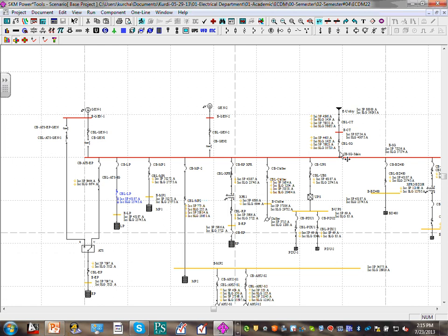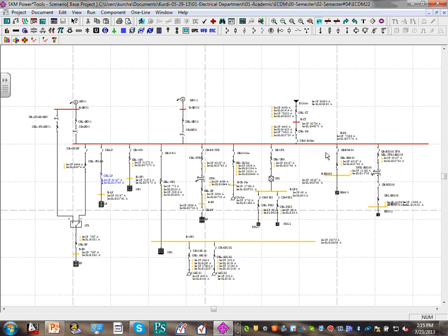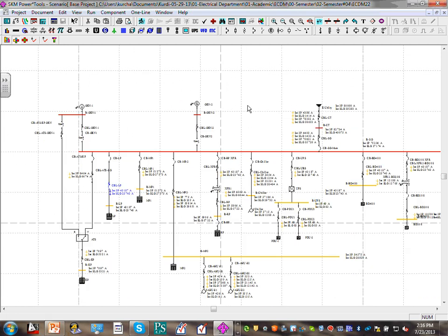In some projects that I was involved in, we run them without the generator, and then we write that if you are to run the generator in parallel with the switchgear, you will exceed the capability of your switchgear. Typically now you cannot run in parallel, right? You can't run except momentarily to switch yourself off the grid. Otherwise, you're going to be in the business of production. And there's a lot of EPA requirements now that prohibit you from running your generators to produce power, right? So we use them as an emergency backup system. Anyway, so that's your riser.